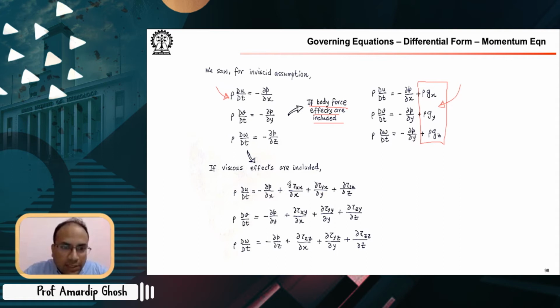Now, I said in the last lecture that here, when you include the effect of viscosity, remember, inviscid fluid, ideal fluids, are where there's no viscosity, but as the name suggests, it's an ideal assumption. In most cases, viscosity is there, but the gradients of velocity are such that the viscosity doesn't manifest itself in the form of forces, because you already saw that tau xx has something to do with dou u dou x, although I wrote du dx, but you understand the sense of it.